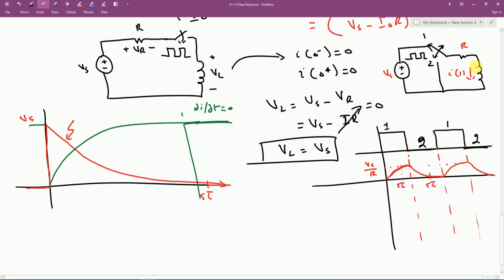And this RL circuit actually is very useful in modeling a basic concept of the winding of the motors, like the stepper motors, or the DC motors, or the induction motors. So we have actually developed a basic instinct. If you see that you are applying some switching pulse like that, and the current is having a rising slope, and then we have a decaying exponential, this means that the circuit has inductance in it, and that it is actually behaving like a first order circuit.